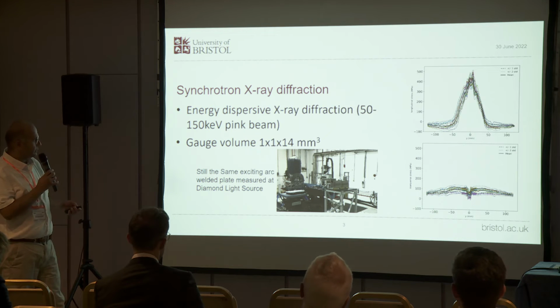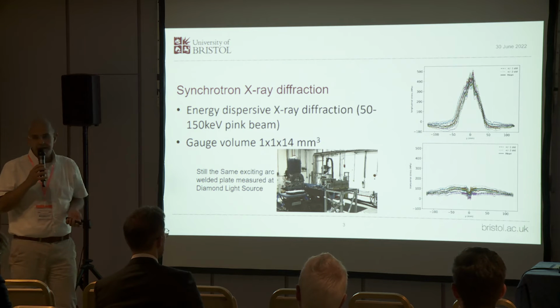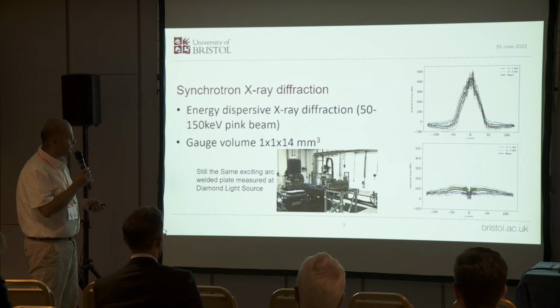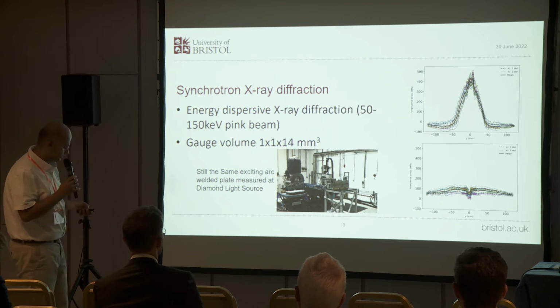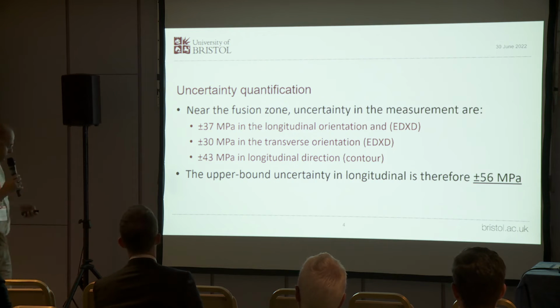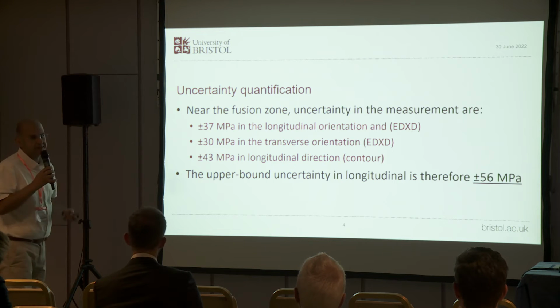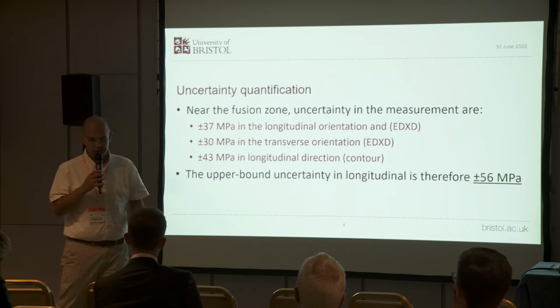I don't think this is very clear here. This is longitudinal, this is transverse. Surprisingly, the guys who are welding things are really good. Despite all the things you have thrown at them, you don't get much variability in the weld residual stresses. Just for good measure, you go and also do all of them with the contour method. I don't want to go through the contour method. You end up with around 56 megapascal plus and minus variability in your weld residual stresses.